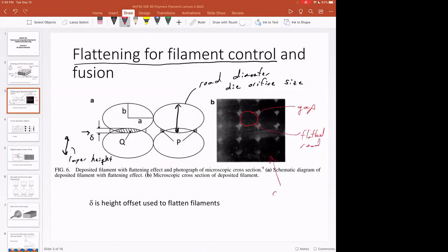And this is a cross section of a printed part. And so here are the layers. So there are the layers. So you can see how this part is built up of these rows. And so that's really interesting, because when you look at an additively manufactured part, you say, well, it's got some ridges on the surface, but it looks like a solid piece of plastic. And it's certainly not a solid piece of plastic inside. You'll talk about infill design and other things you can do with additively manufactured parts in terms of design and shape in some of your other classes.